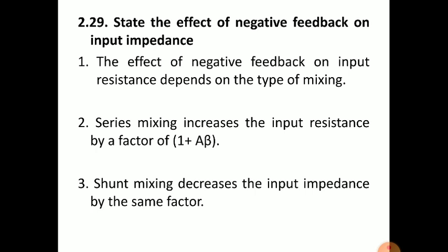If you can remember the block diagrams of the voltage series, voltage shunt, current series or current shunt amplifiers, there you can see the sampling and mixing networks, how they are connected either in shunt or in series, and what happens to the input impedances or output impedances.